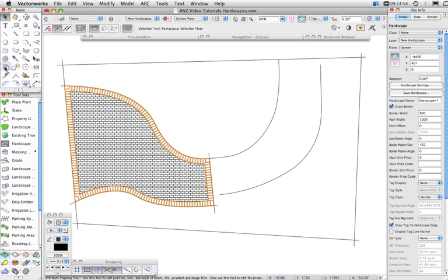This is the attribute mapping tool here, and you'll see the little bounding box that has appeared here represents one instance of this hatch. And if I move this around, the hatch will move, but more importantly I can scale the hatch. So if I click and drag on the corner here, you'll see the scale factor coming there.